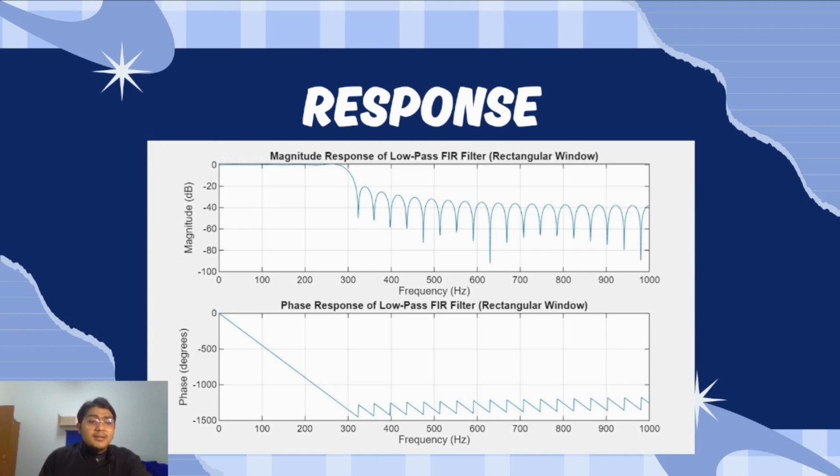In the stopband, the phase appears erratic, but that's expected because the signal magnitude is nearly zero, making the phase mathematically undefined. We simply ignore that region. In summary, the rectangular window low pass filter gives a sharp transition and linear phase, but suffers from oscillation in the stopband that limits its ability to fully block unwanted frequencies.